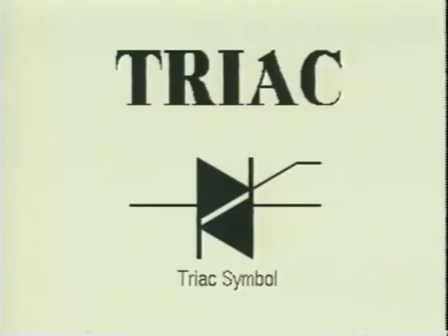Here we see the triac. The triac is essentially two inverse parallel connected SCRs with a common gate. This allows the triac to conduct current in both the positive and negative directions. Let's briefly look at the operation of the triac.